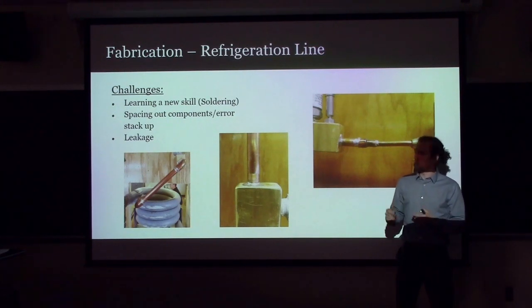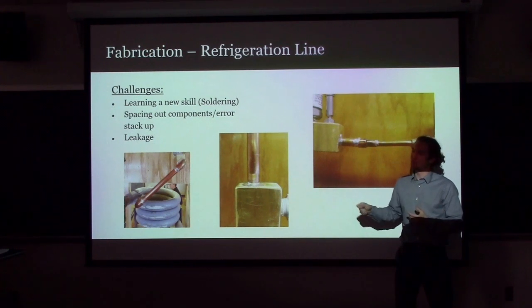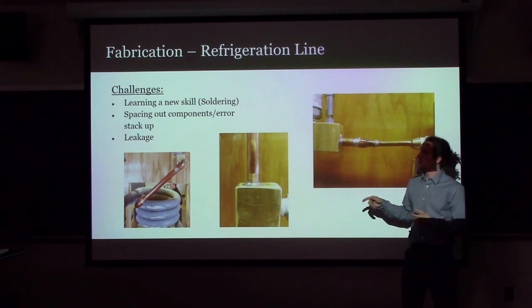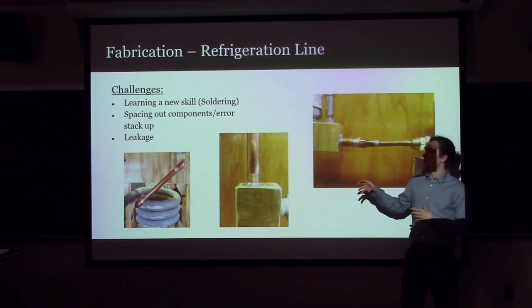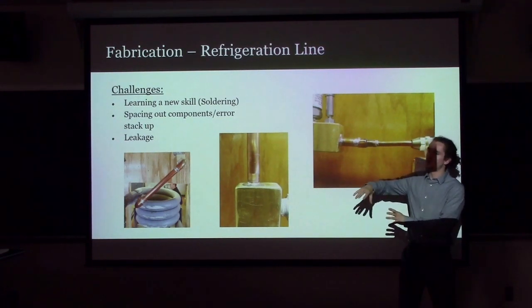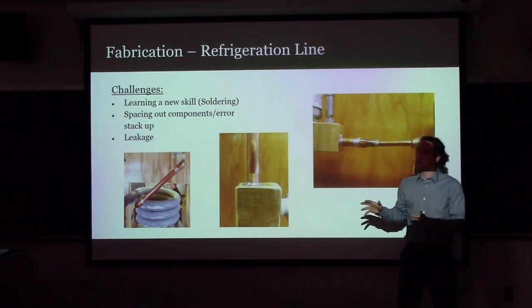Another thing we had to deal with was the sensor ports again. They were very large, so you had to heat them up for a long time with the torch before you were actually ready to solder. That meant that we had to solder them individually, starting with those being the first piece, solder everything off that, and then put it on the board to do as little heat work around the board so we wouldn't make it catch fire or anything.